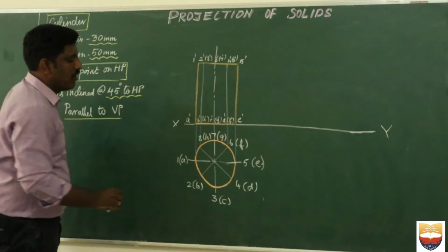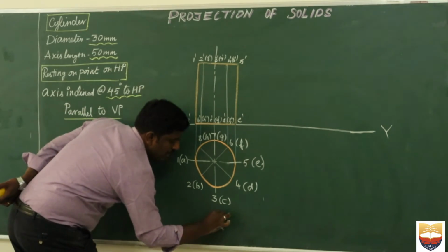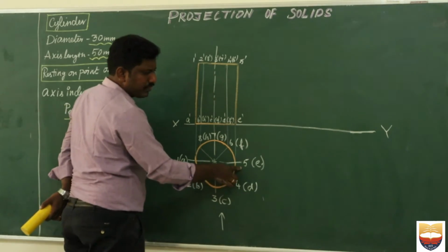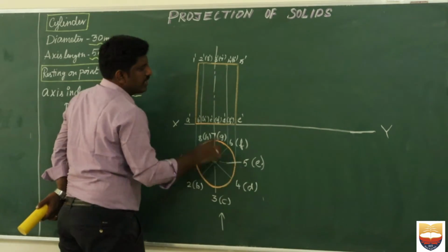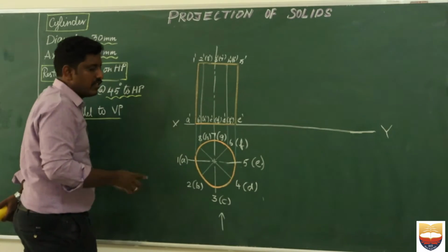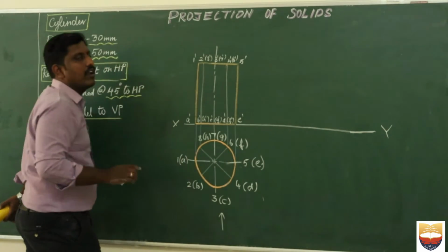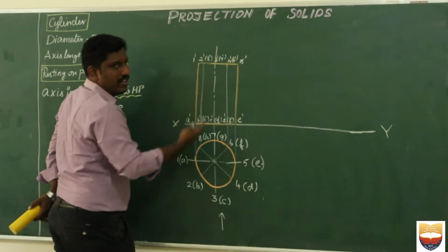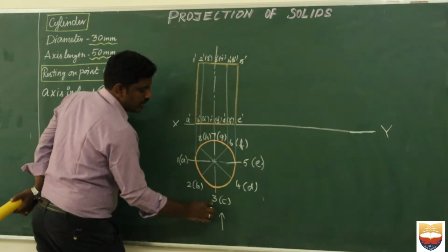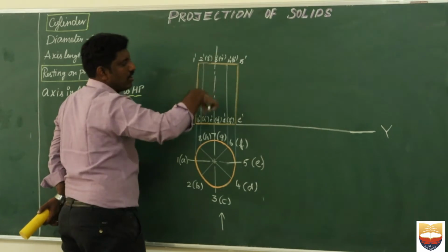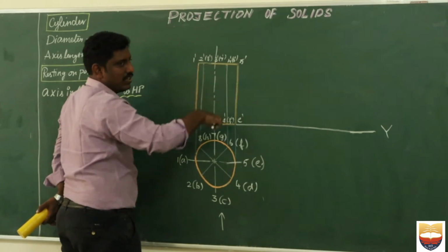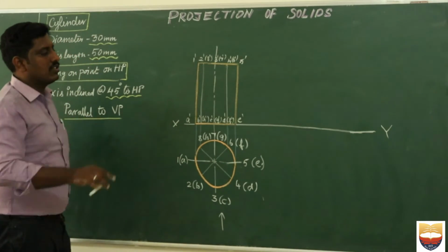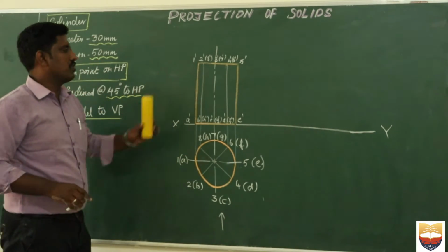You should be very careful. When I look from here I can see 1, 2, 3, 4, 5, but I have drawn only 1 and 5 dark here. The reason is that all the other remaining lines are imaginary directrix lines for me, so I should not draw all these very dark. On the image you see here that 3 and 7 are not drawn dark, since I have only my center line. It is a procedure similar to that of a cone. The cone and cylinder follow the same procedure. This is about your simple question.